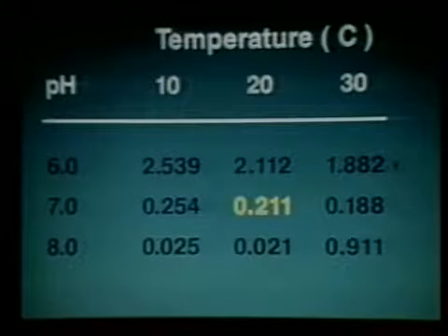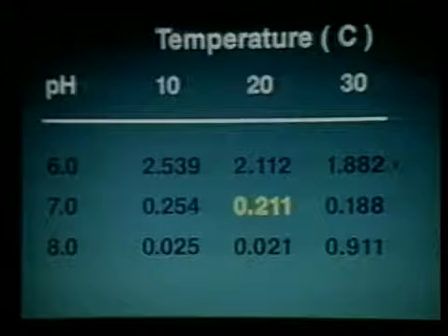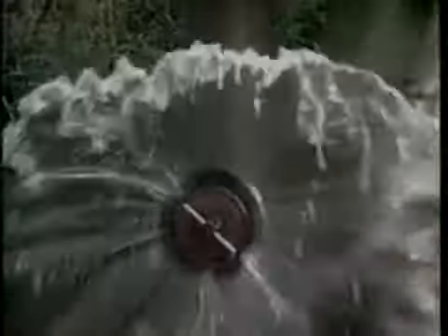Note, as the pH decreases, the factor gets larger, which shows that more carbon dioxide is present in acidic waters of similar alkalinities. The table shown here is condensed for convenience. However, tables showing factors for a wide range of pH and temperatures may be obtained from your county agent or aquaculture specialist. If carbon dioxide levels are elevated, it is usually due to inadequate aeration of groundwater or following a phytoplankton die-off.